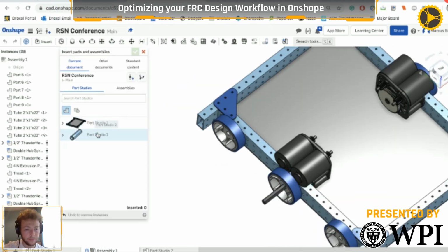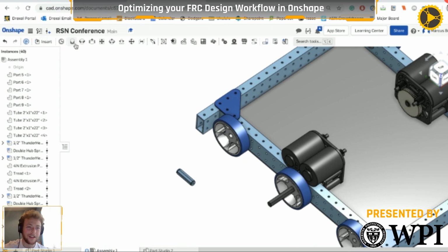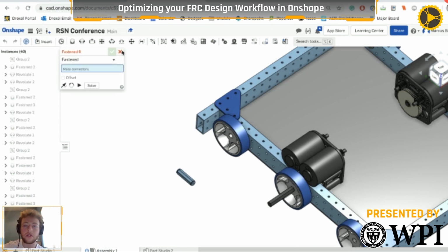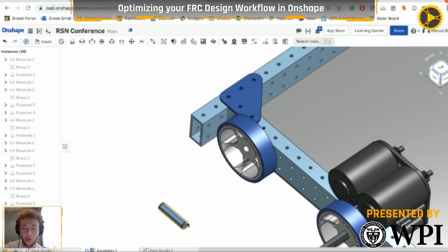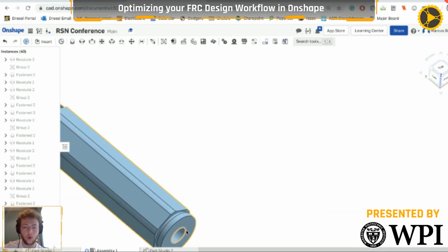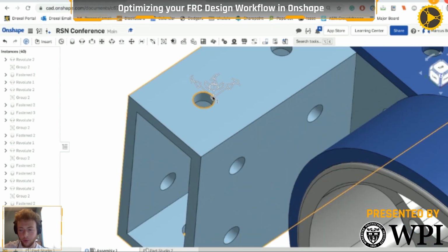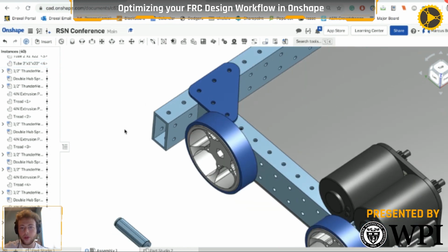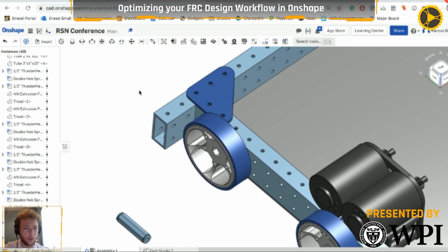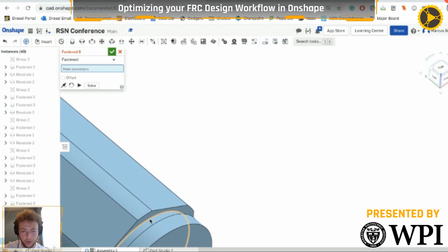Oh, okay, cool. Yeah. Got it. I apologize. My team hasn't used a quarter 20 in years, so I'm not down with quarter 20s at all. I don't remember any of the numbers. So our standard hole size on 1836 is quarter 20 tap, or it's a little bit oversized for a 10-32 through hole. So you'll notice it just gives us a little more clearance, a little more wiggle room. We also use it for rivets. I don't even remember what size, but it's a common hole. It's number 7, I believe. That's what we use very often.